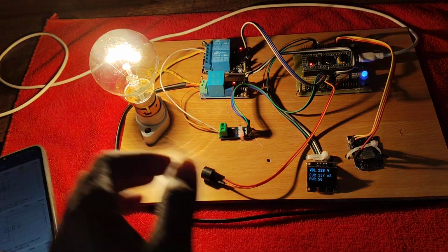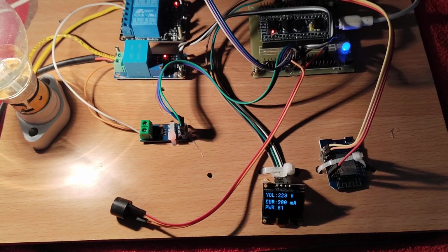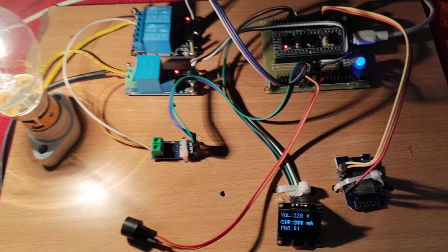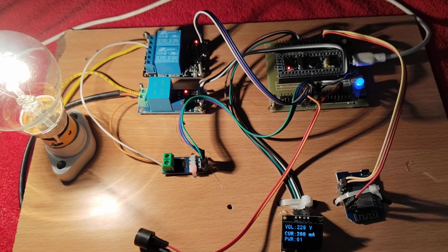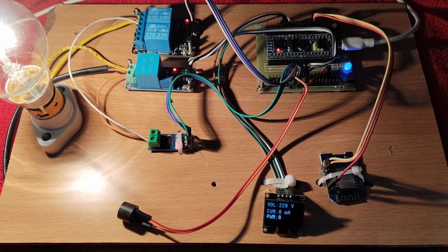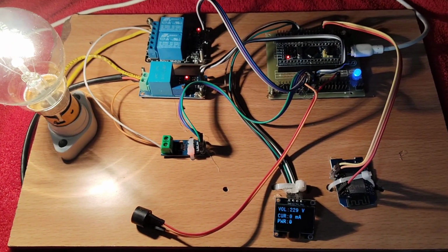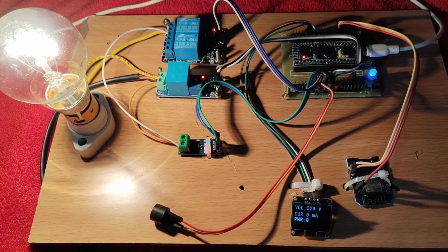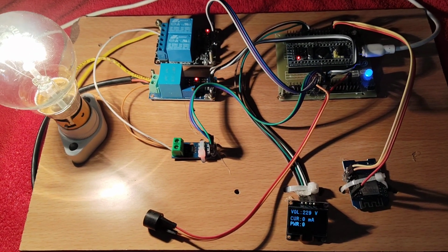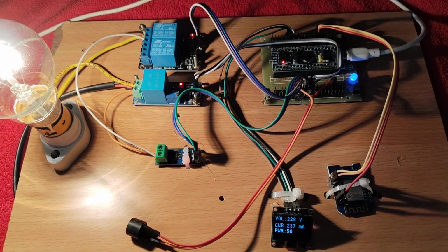We have also placed a buzzer that gives a siren when overload or overcurrent situations occur. The threshold values in the code are that if the voltage is less than 50 volts, or the current is less than 80, the values are set to 0, which helps to filter the noise.